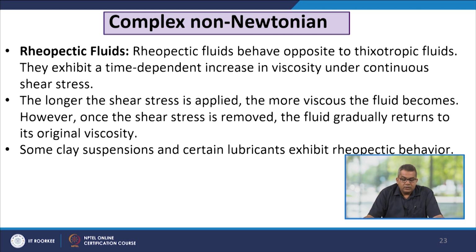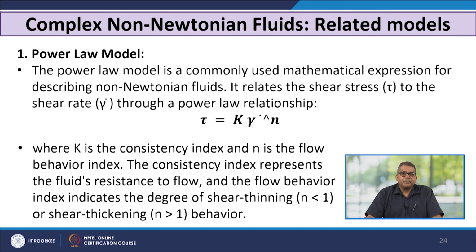Rheopectic fluids. The rheopectic fluids behave opposite to the thixotropic fluids, and they exhibit a time dependent increase in viscosity under continuous shear stress. The longer the shear stress is applied, the more viscous the fluid becomes. However, once the shear stress is removed, the fluid gradually returns to its original viscosity. Some clay suspensions and certain lubricants exhibit rheopectic behavior.